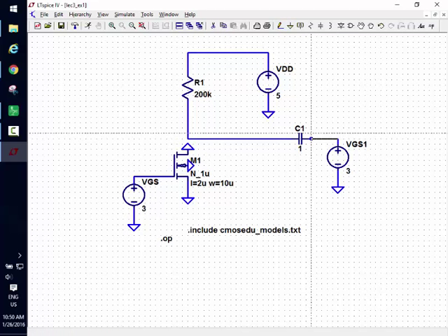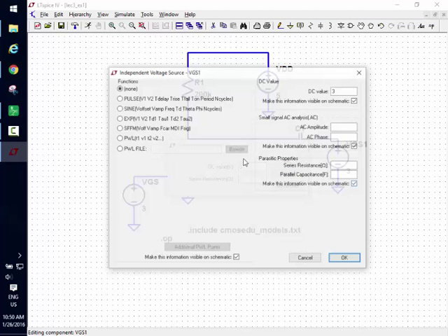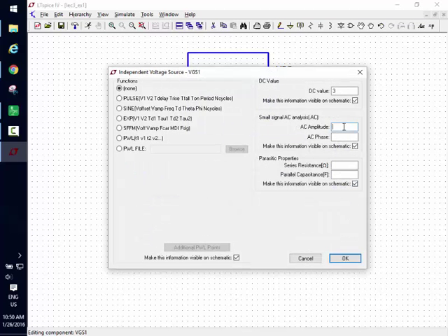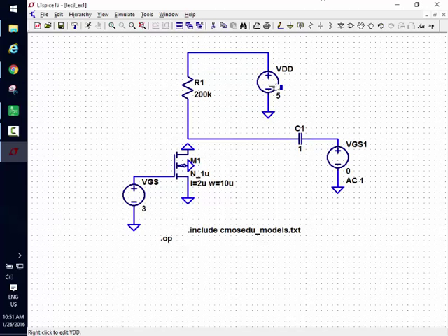And let's go over here. And let's go advanced. And does it matter, since I'm going to do an AC analysis, that I set the DC value here? It doesn't matter, but you know what? I don't like it, so I'm not going to use it. We'll just put it at 0. And I put 1 because in an AC analysis, the amplitude doesn't matter. And using 1 volt, because it replaces an AC analysis, it replaces all the active devices. What's an active device? Transistor, a MOSFET, with its equivalent resistances and capacitances and voltage control current sources and all that. The linear stuff that you learned.